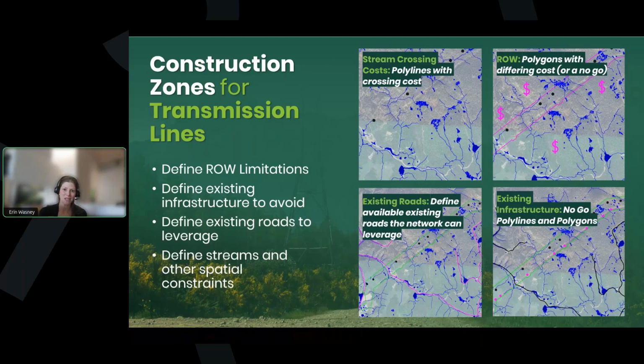The same can be done with other types of geotechnically unstable areas. Maybe you've got a protected habitat. Lots of ways to leverage construction zones in order to control the behavior and influence how Path Explorer behaves. So that's kind of the second part of our webinar. So terrain modeling, then we're going to go to Path Explorer, and then from there, we take it over into our second module, and we're going to do our detailed road design.